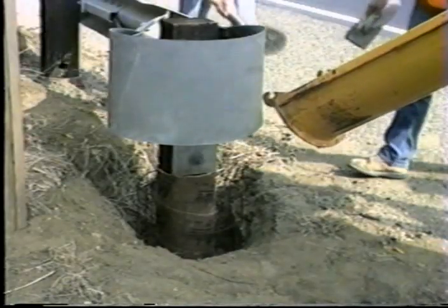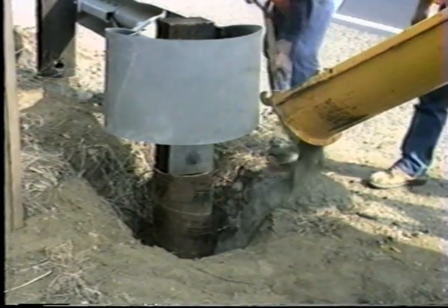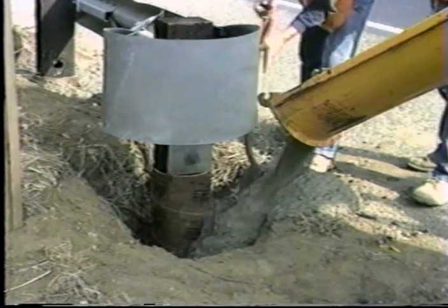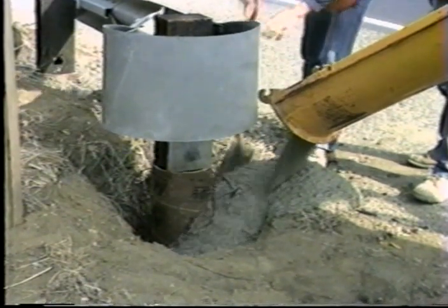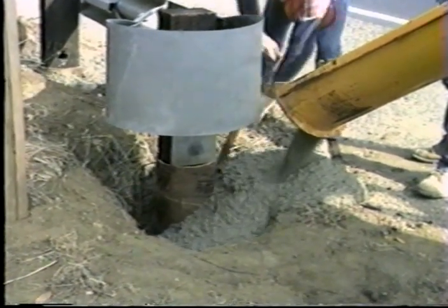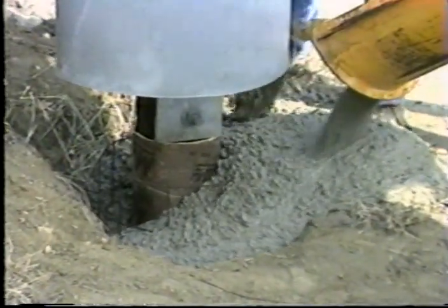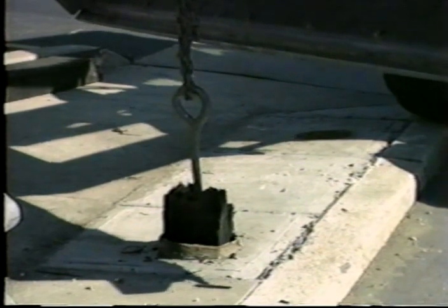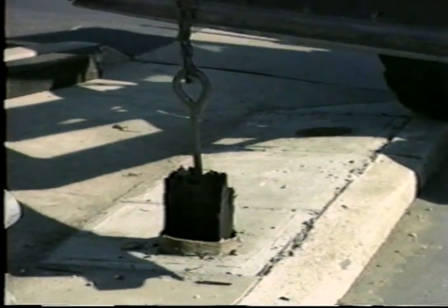To ensure that the first and second posts of the system break away and are not pushed over when impacted, they're set in concrete footings of at least 3-foot depth. The surrounding soil must be stable. A loose sand will not work. Removal of broken stubs has created some problems, with several solutions being worked out.